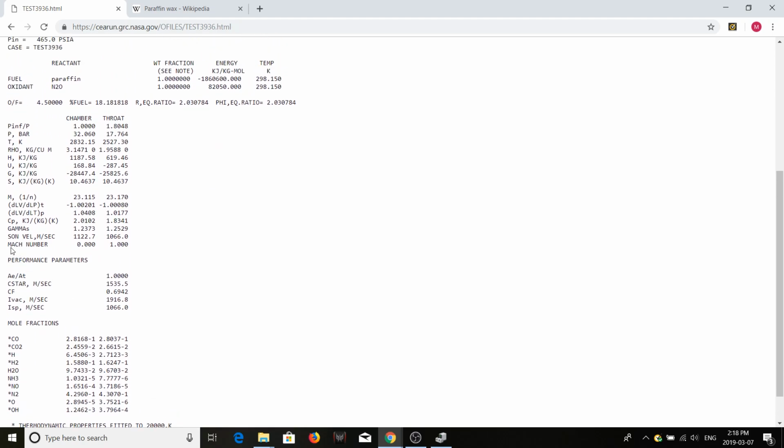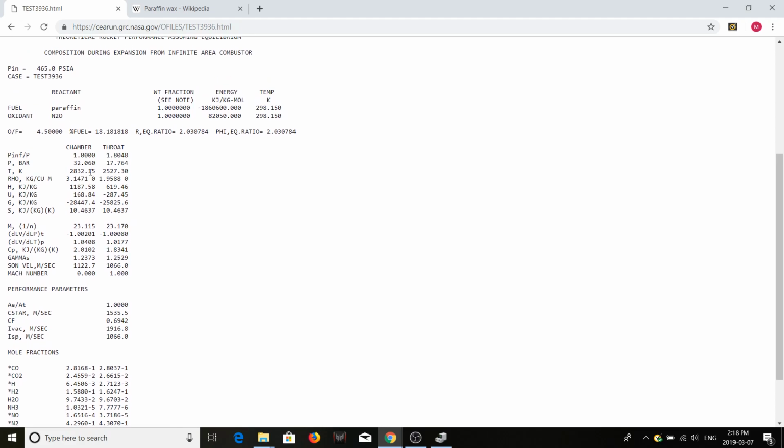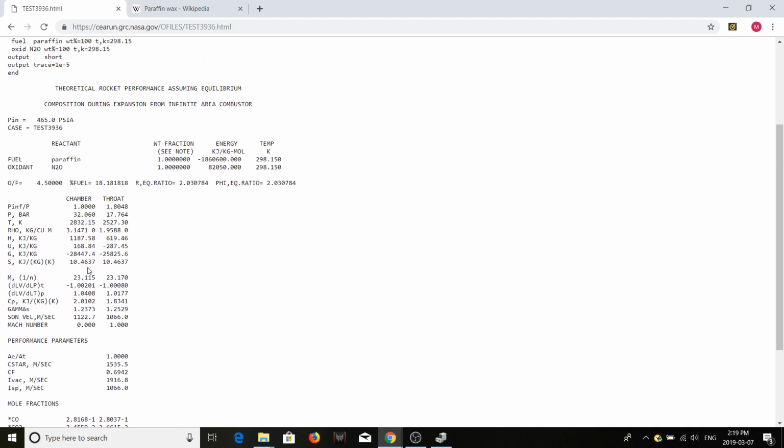That's what you get. So the important ones you got are gamma here, which is your ratio of specific heats at different points. Does change, not by a lot. So in theory, you could assume it was constant, and if you're just doing calculations on paper, assuming it was constant, at least up to the throat, wouldn't be a gross exaggeration, but in reality, that wouldn't hold up. So thinking that sonic velocity is the same is obviously not at all correct. Yeah, so gamma is an important one.